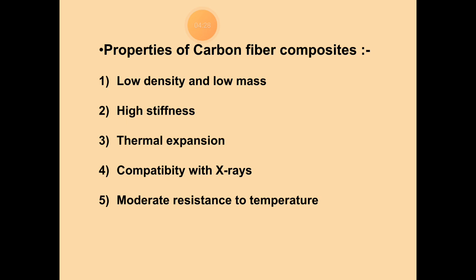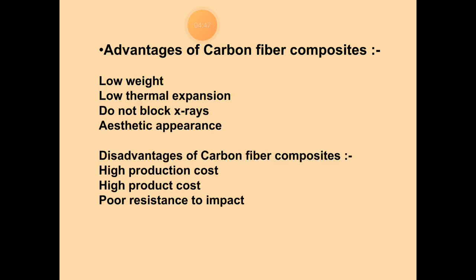Now, with compatibility of X-rays, it is used in the healthcare industry. It does not block X-rays. For moderate resistance to temperature, most carbon fiber composites offer resistance to temperatures of 70 to 120 centigrade. Then the advantages of carbon fibers: low weight, low thermal expansion, do not block X-rays, and aesthetic appearance.